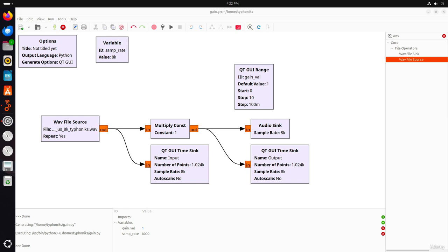The placement of this cutoff frequency depends entirely on the filter's design and the needs of the application. For instance, in audio processing, the cutoff might be 2 kHz to separate bass sounds from treble. In radio frequency communication, the cutoff could be at several megahertz to isolate a specific signal band.